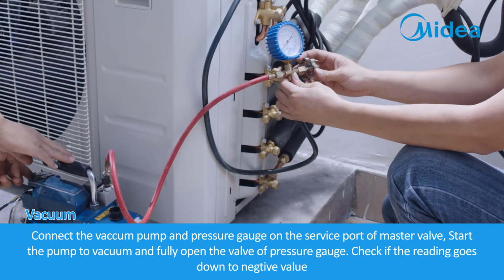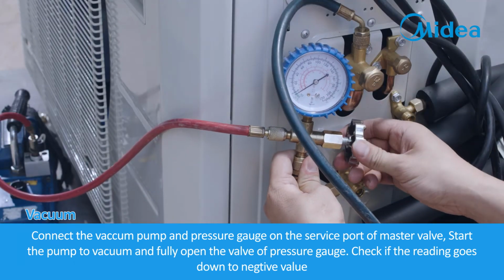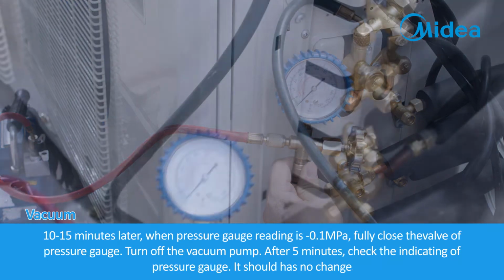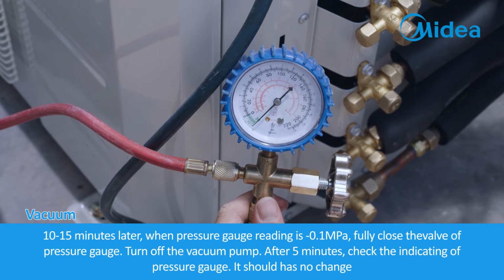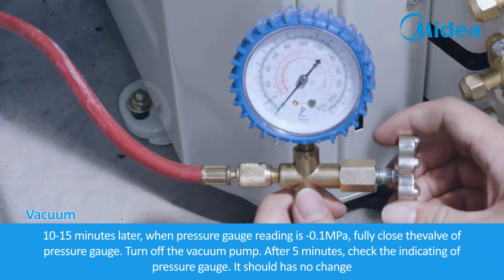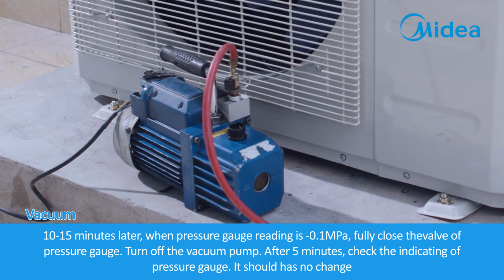Start the pump to vacuum and fully open the valve of pressure gauge. Check if the reading goes down to negative value. 10 to 15 minutes later, when pressure gauge reading is minus 0.1 megapascals, fully close the valve of pressure gauge. Turn off the vacuum pump.